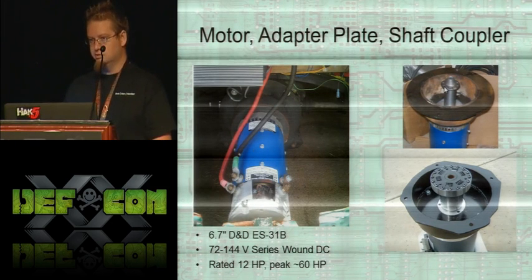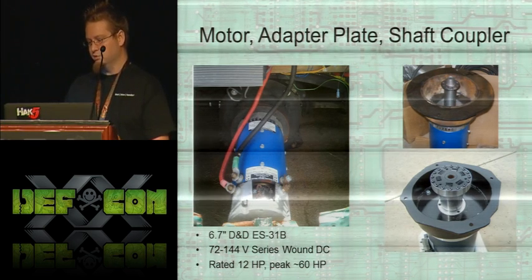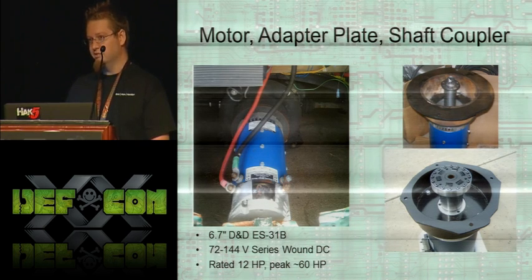This is what my original shaft coupler looked like. It's basically part of an old clutch disc that gets welded onto a coupler that goes onto the electric motor. After a couple thousand miles, the teeth on mine got worn off, so I had to replace it with one of these springy types. They're supposed to be a lot better and last better.